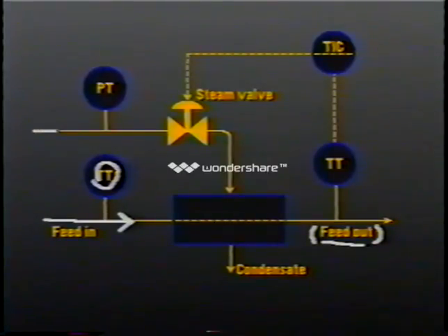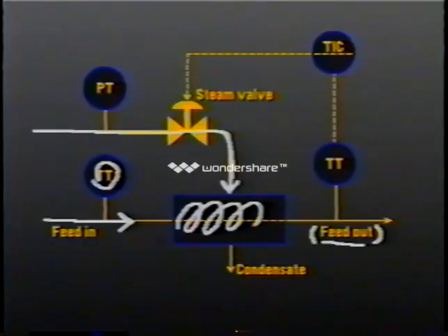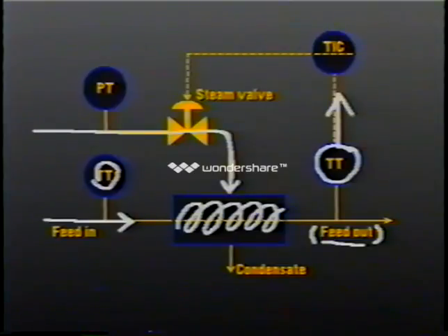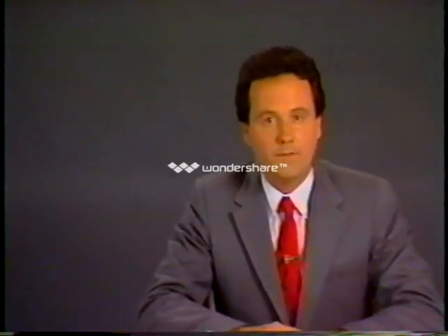The second load, which is the steam flow, could change very rapidly, causing a quick and substantial change in the steam temperature. We will also encounter a big lag as the steam heats up the pipes in the exchanger at the heart of the heating process. This significant lag in the temperature process could make the control loop difficult to stabilize. Another assumption we will make is that the downstream temperature transmitter is located close to the heater so that dead time is negligible. Now let's look at the block diagram of the system.